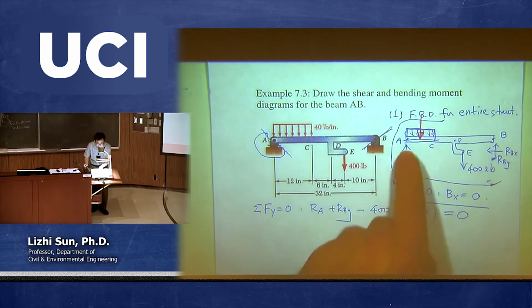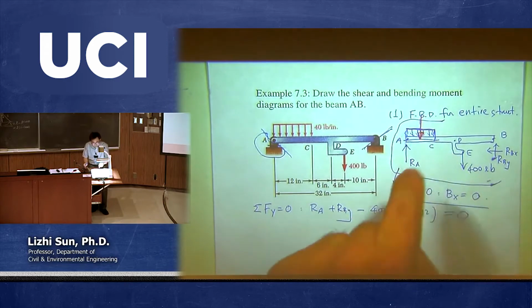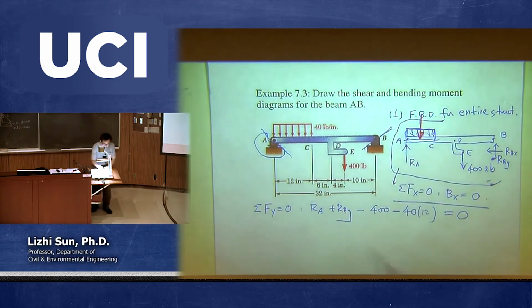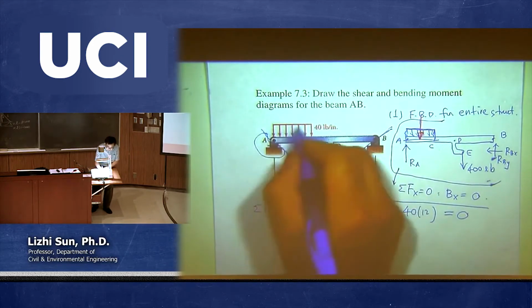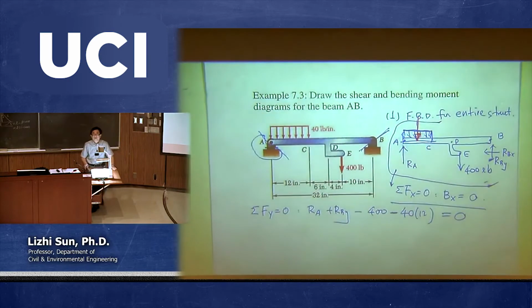Okay, so keep in mind, you can only do the equivalence after you plot the free body diagram. So don't say this one in the original structure, you say that's equivalent to a concentrated load. In principle, that's not true. Okay, so that's the equation having two forces involved. There's nothing we can do. We just leave that equation there. So we're going to come back to use that equation.